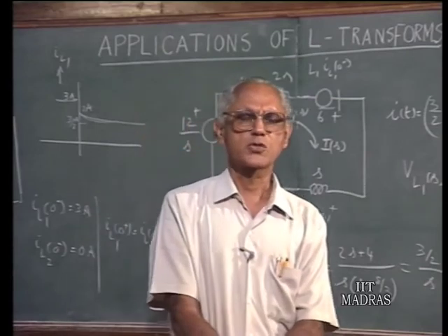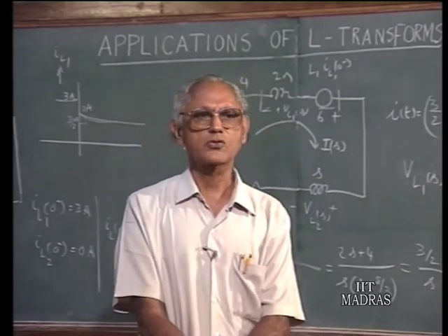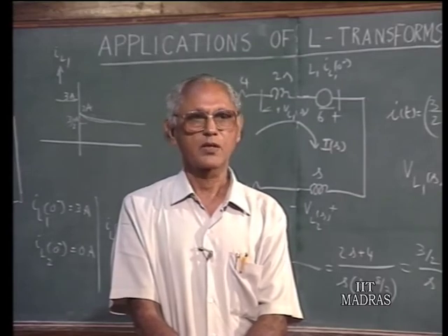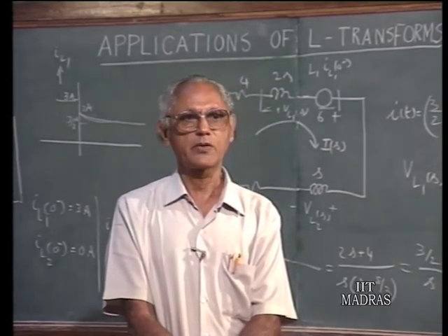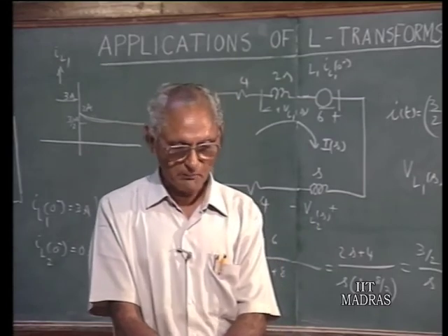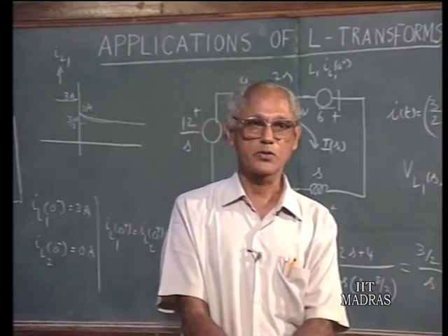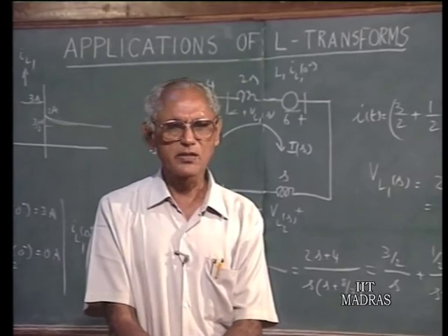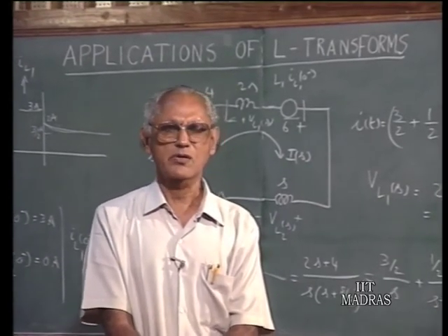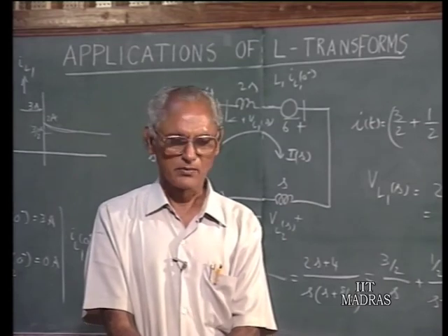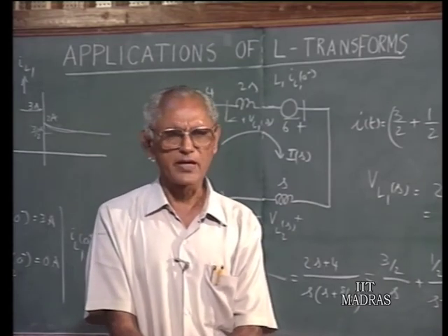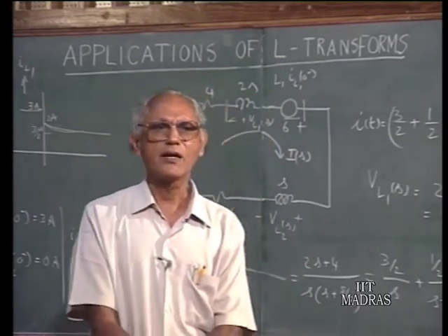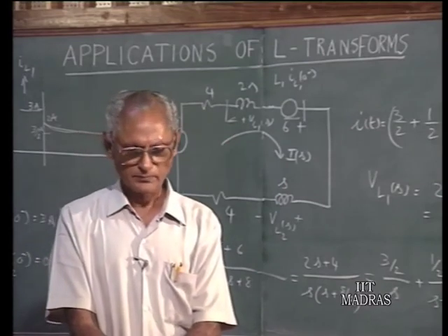It certainly is a more fundamental approach. So, one should also know how to handle transient problems using the classical differential equation approach. Even though Laplace transform has a lot of advantages and we for the most part resort to Laplace transforms, one should not completely ignore or forget the differential equation approach to the solution of the transient problems. Particularly in very simple cases, you can write down the differential equation solution by mere inspection. You do not have to transform those equations every time. So, it is a powerful technique, no doubt, but in very simple cases, the straightforward application of differential equations will fetch you the result quickly and also with a little bit of insight into the working of the problem.